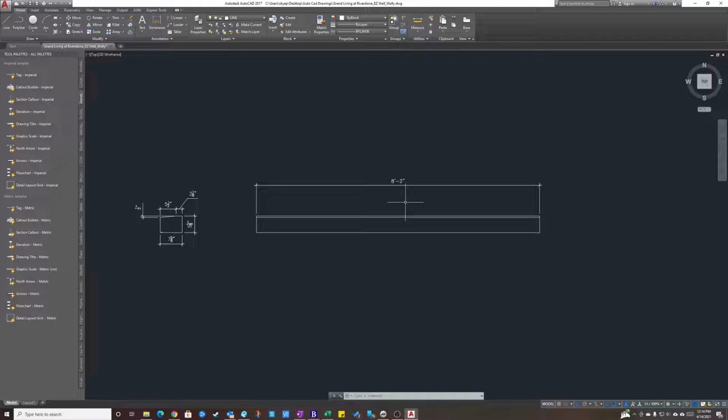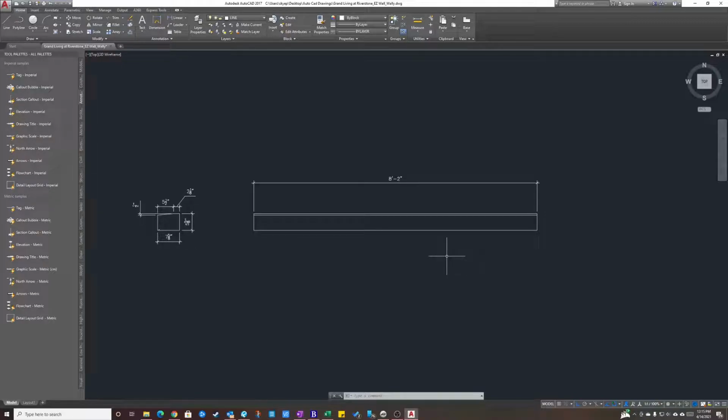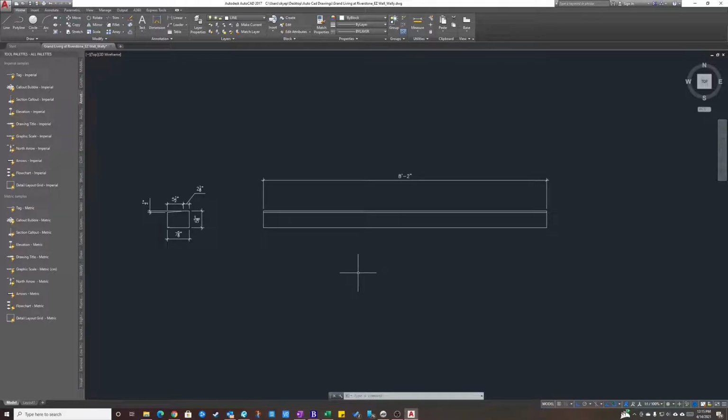A good rule of thumb says that you don't really want to make anything over 4 feet long, especially this particular size, because the skinnier and thinner it is and the longer it is, well, basic physics says that it's going to be easier to break. So what do we do? Well, logic would say that we need to break this into 2 pieces. And I will show you that in just a moment.